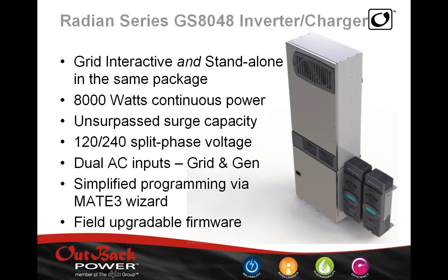It's 16.9 kVA. So it can handle loads like a starting motor, for example, that are known for having very high inrush currents, depending on the rotor design. So it'll handle those types of loads.